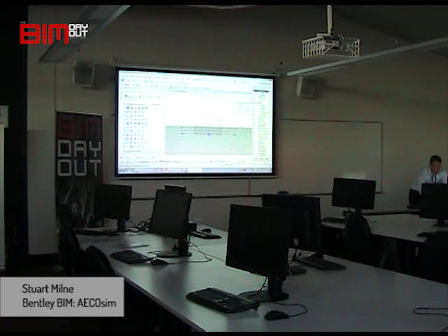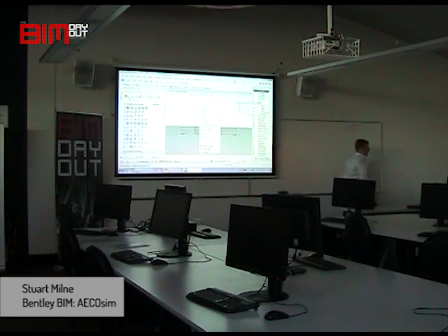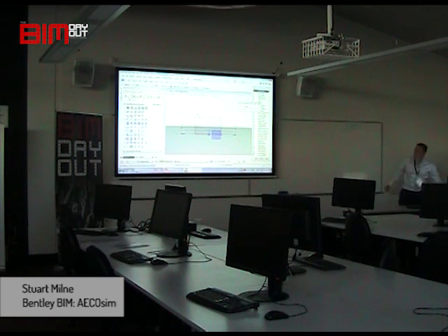The copy tool is in 2 locations. One over here on 3, or you could hold down your right mouse key in vacant space on the screen, and this little toolbar appears. It gives you some common tools, one of them being copy. Grab the copy tool and click on the base of the cube here once. You'll see hanging off your cursor we actually got the cube, but we want the space. So click your right mouse key, and that alternates through any objects that are overlapping. Just click the right mouse key once.